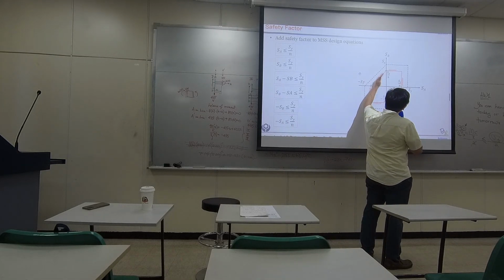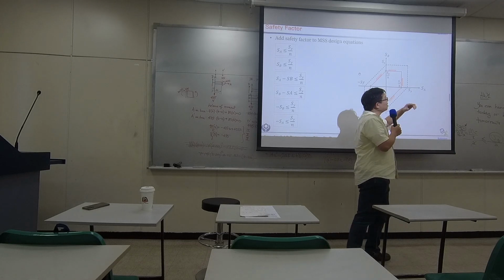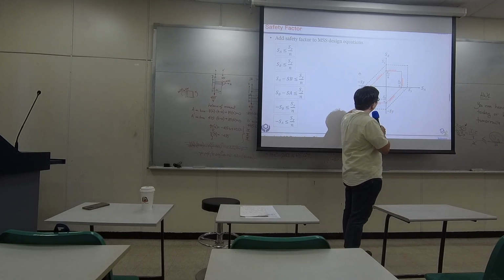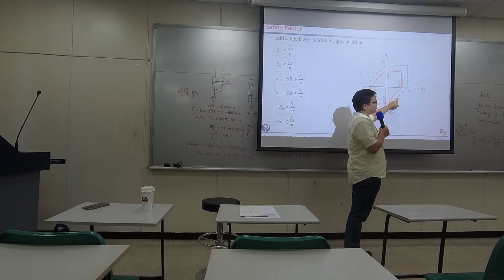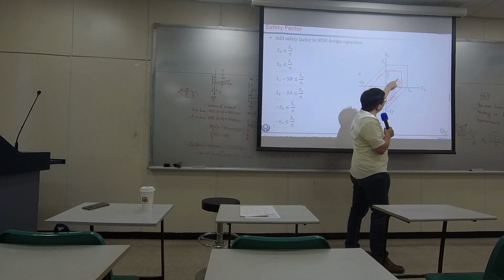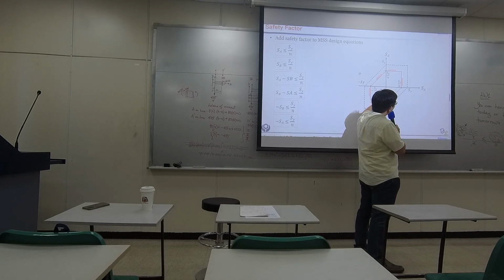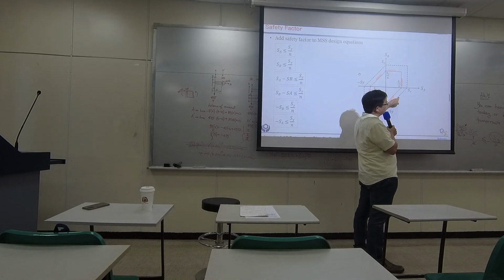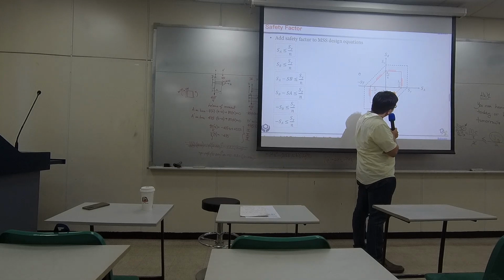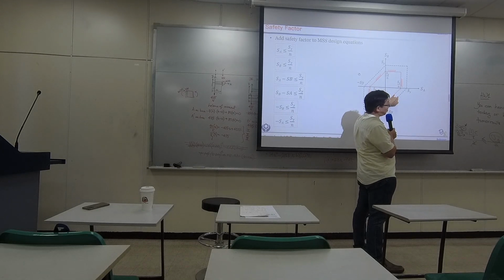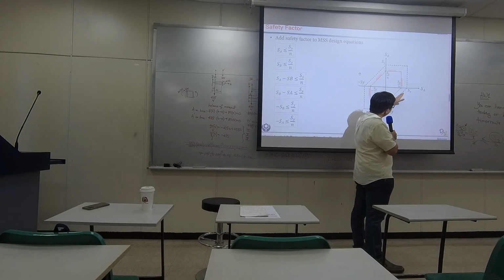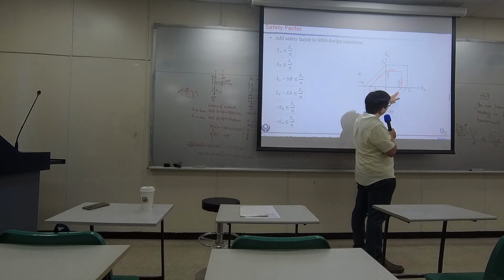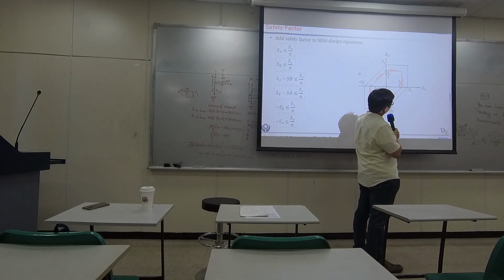So why do you do that? Because you want your design to be a little bit further away from the edge. Your design region becomes smaller, and you cannot get close to the edge. Okay, so this is the area you want to avoid. You cannot go further here because you will definitely fail. On the dashed line, you are about to yield, but you stay away from yielding. You keep a safety distance.